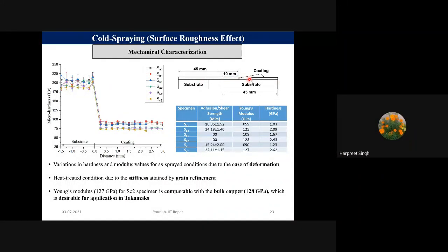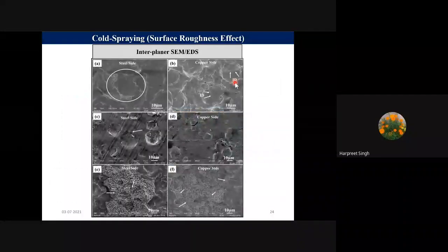When the material fails, we get two aspects: one is the coating side, another is the substrate side. When you pull it, you will get this exposed surface, which was earlier coated, but now no coating is there. And then this was the coating which was sticking on the surface, but now you have detached it, and then this surface. That is where we did this SEM, to see what is happening at these surfaces, right?